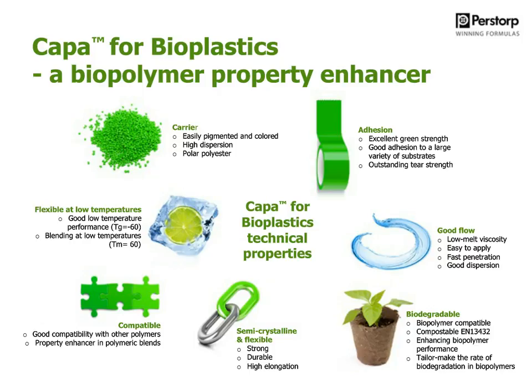As I mentioned, it's easy to apply, and it has good penetration as well as good dispersion. This you can balance against the different grades and melt flows and your application, of course. And you will then have a biodegradable hot melt for your packaging.